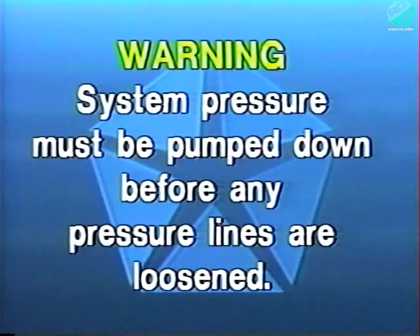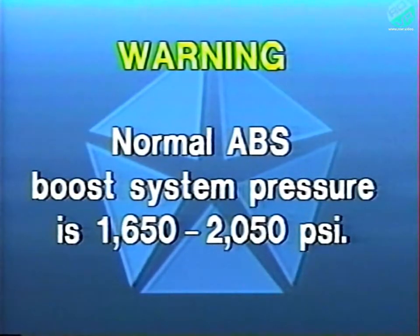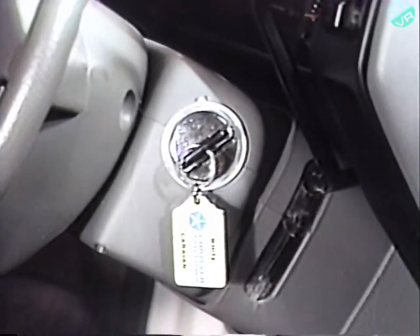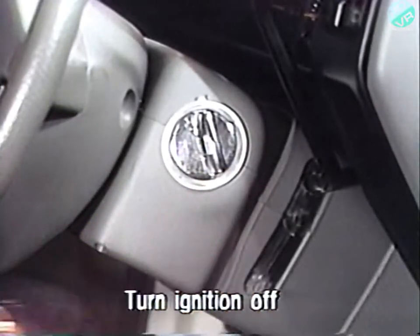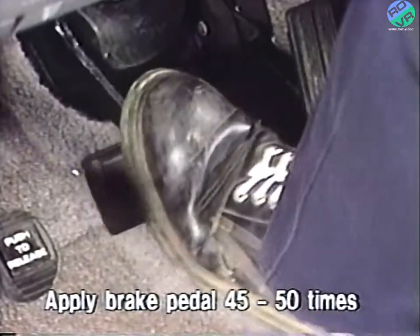To begin the hose replacement service procedure, the system pressure must first be pumped down before any pressure lines are loosened. You should be aware that the normal working pressure of the ABS boost system is 1,650 to 2,050 psi. Failure to reduce the pressure could result in personal injury. To reduce the system pressure, turn the ignition switch off and apply the brake pedal 45 to 50 times until the pedal becomes firm.